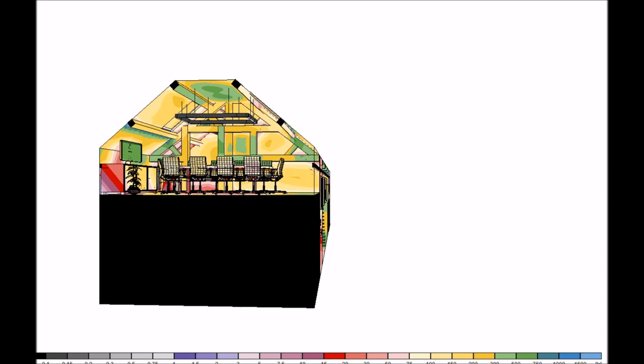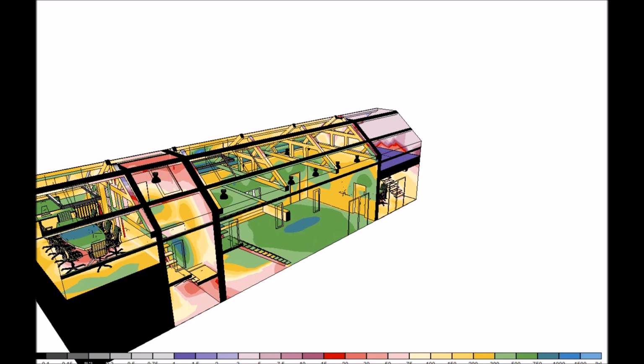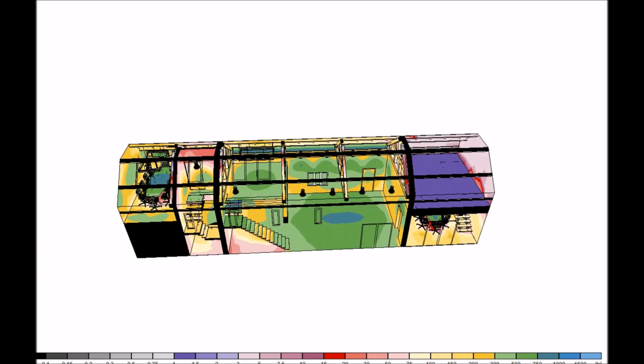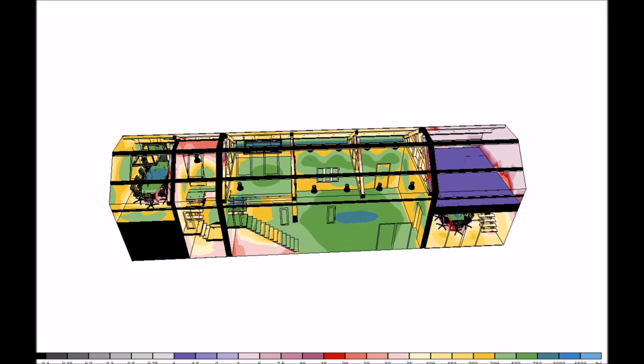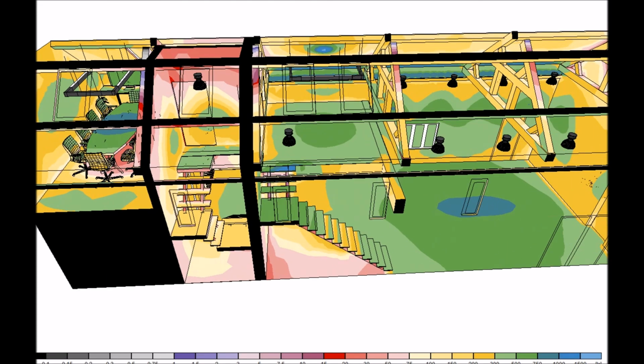So that's all good. And then very lastly, to finish off, the stairs with those 2 pendants, you can see we want to hit at least 150 lux, which is these orange tones, so we're getting that for the stairs off those 2 pendants, so the emergency versions of those should cover those.